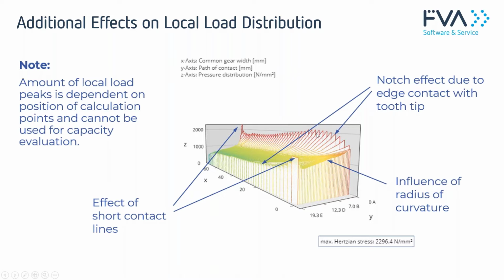You have to take this into account when you design a gearbox, and you have to take measures to avoid those local load peaks. If you have a helical gear and you do not apply a sufficient tip relief on your teeth, this will result in exactly these load peaks, and in many cases you will then get triangular flaking, which starts at the contact position of the tip within the root of the driving gear.